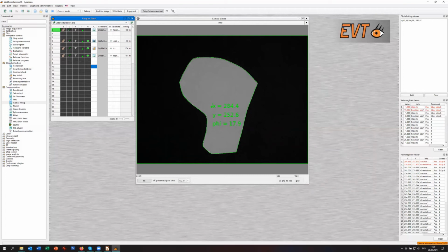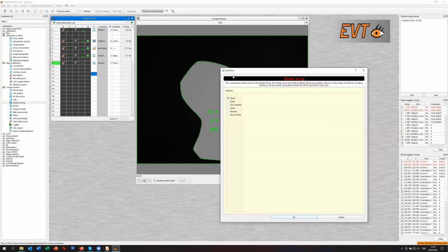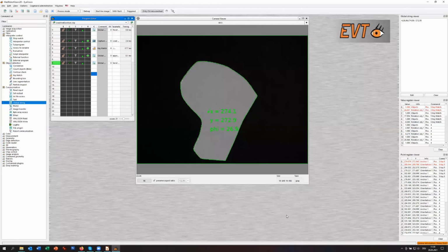And if you have a very simple robot control, you simply could send it out to the robot by simply send. And if you have the robot connected to a TCP/IP or UDP network, you simply take the IP address, and that's it. So you can simply send out this position. Of course, the first important step is always after you have done the hand-eye calibration.